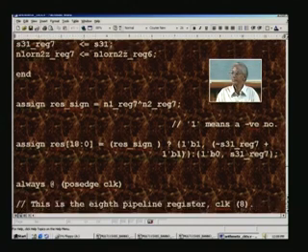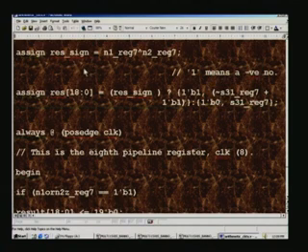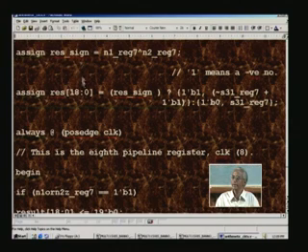And here there is also the final result. We said right in the diagram before, in the partitioning diagram, that 18 through 0 is the final result, which is the product of the two numbers N1 and N2. We have done the entire algorithm which we computed using this Verilog code so far, and it handles only the magnitude as mentioned before, and we have just now evaluated the sign of the number. So based upon this sign bit, we will manipulate the final result by reflecting the 2's complement or keeping the number as it is.